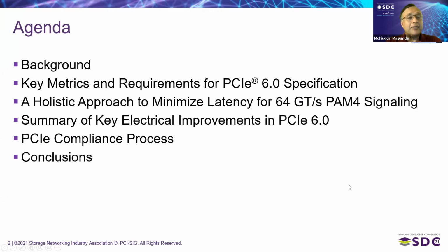So I will give you a little bit of background on the PCIe technology and how it is evolving. And then I will talk about key metrics and the requirements for the PCIe 6.0 specification, how we use a holistic approach by optimizing electrical, logical, protocol, and all aspects of this technology to minimize latency for 64 gigatransfer per second PAM4 signaling.